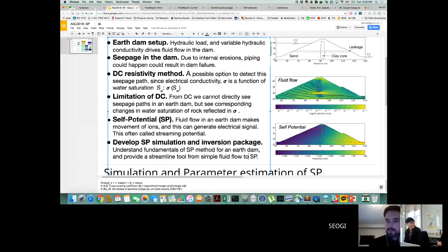So how did you set up that model? I set up a boundary condition here. I put a Dirichlet condition, and then a Neumann condition until here, on all those boundaries. There are a little bit of details, because I had to define the boundary condition inside of your mesh. So I'm actually not solving this part, but only solving inside of your mesh. So this is a tensor mesh? Yeah, it's a tensor mesh. Basically zeroing out things. Yeah, exactly. It's a little bit annoying.